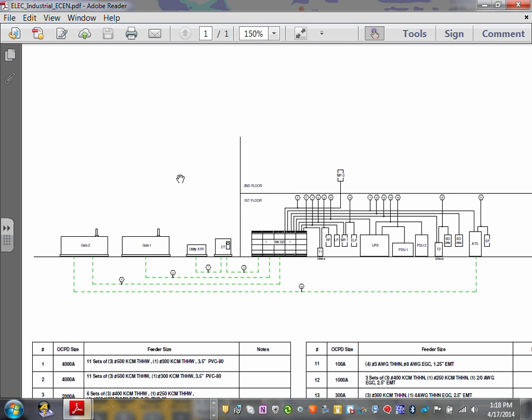So if you have a room like this full of computers in part of that building, you need to allocate a load associated with a feeder that feeds this UPS, which in turn feeds PDUs to feed the computer racks, if any. So that's what you're seeing here. We're bringing my power from here into that switchgear, and that's my main panel. We have a UPS that feeds PDUs, two PDUs here. We have a receptacle panel. We have a lighting panel and mechanical panels over here.